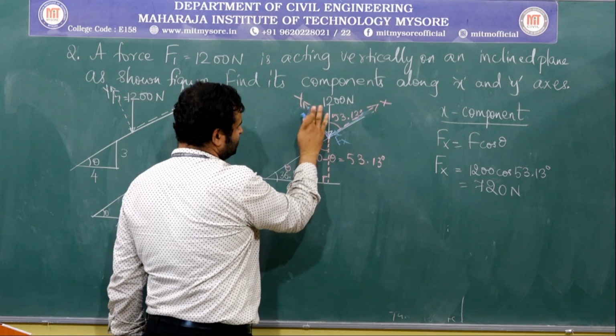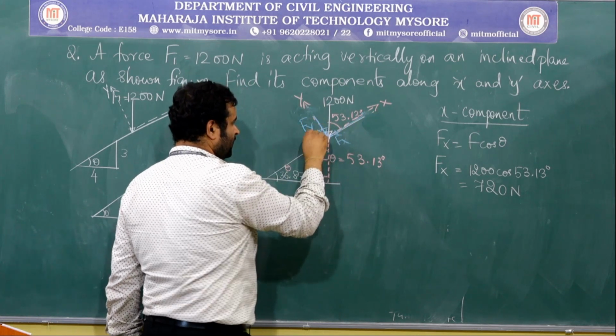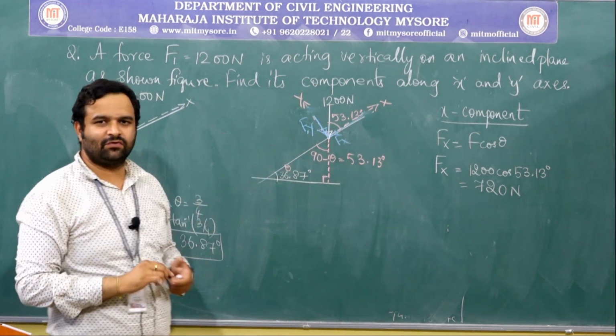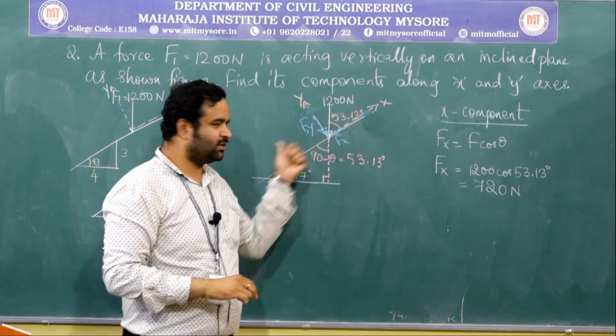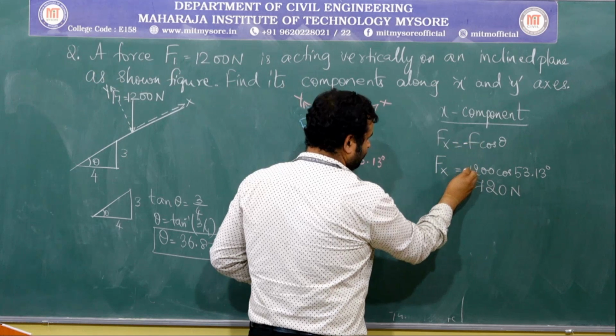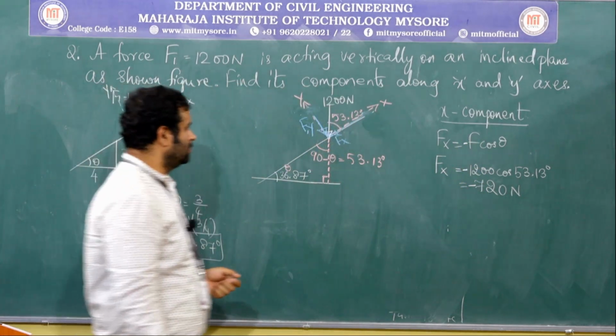Here change the arrowhead. This is fy. Now, the sign convention for fx is minus because it is measured towards left. Minus 720 Newton.